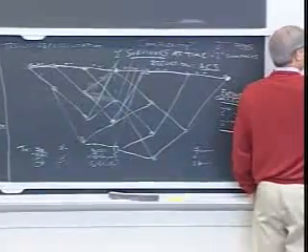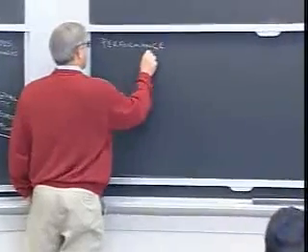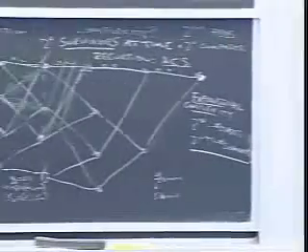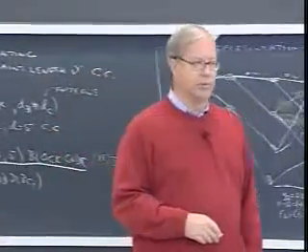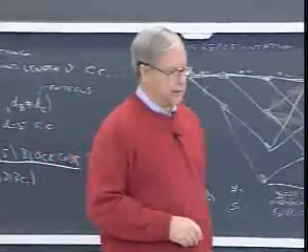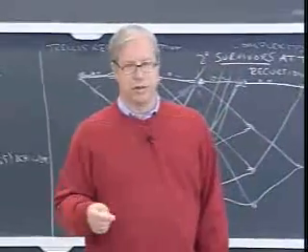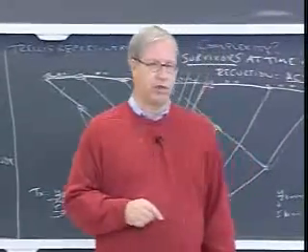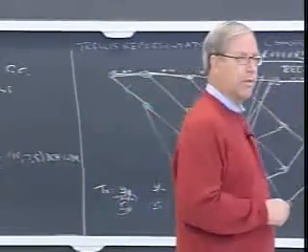So the last topic is to talk about performance. How are we going to evaluate the performance of convolutional codes? You remember what we did on block codes? We basically looked at the pairwise error probability between block code words. We then did a union bound based on the pairwise error probabilities, and we observed that the union bound was typically dominated by the minimum distance error events, and so we got the union bound estimate, which was purely based on the minimum distance possible errors.